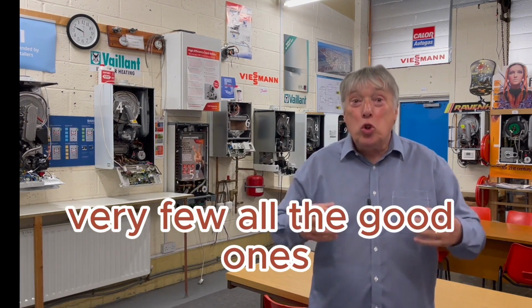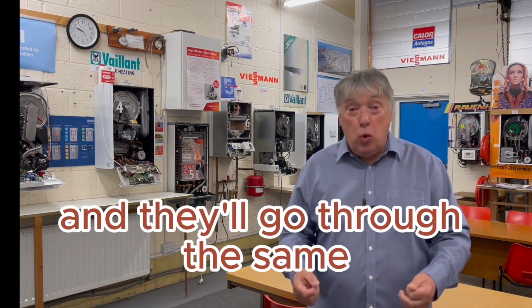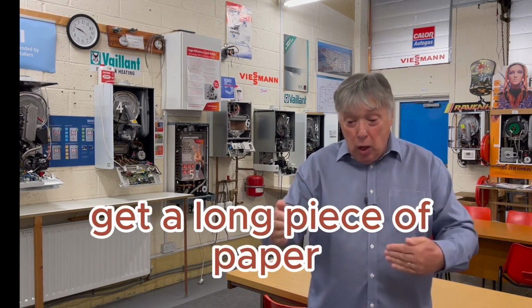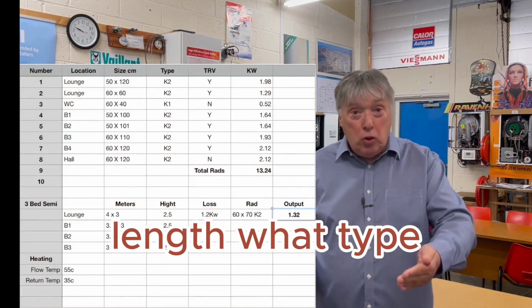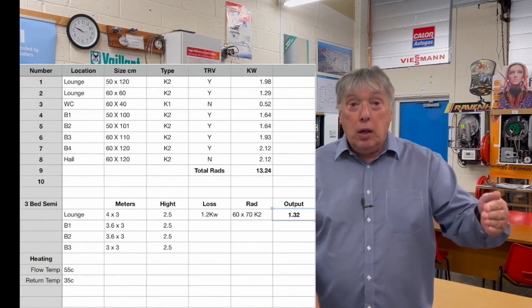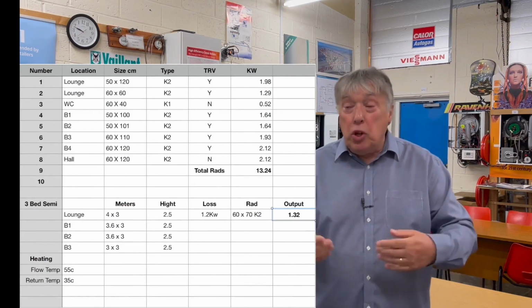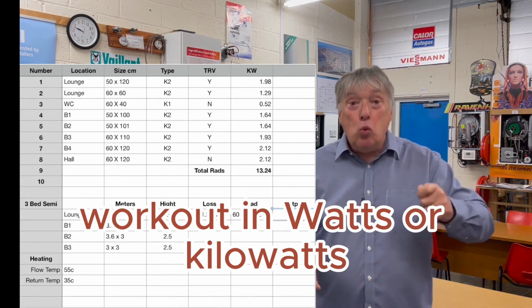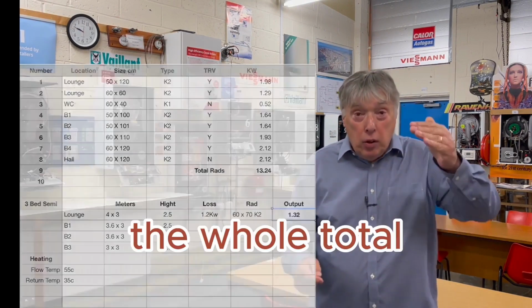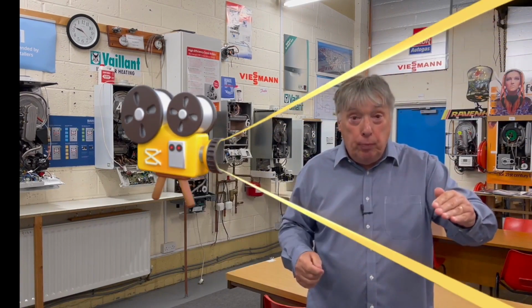Very few, all the good ones, hopefully the factory trained ones, they will actually do this. And they'll go through the same as I suggest to you. Get a long piece of paper, start from the hall as always, height, length, what type? Dining room, kitchen, bedroom 1, 2, 3, 4, whatever, utility room, downstairs loo, all of the radiators, work out in watts or kilowatts, the whole total. And then that figure goes into the boiler output.